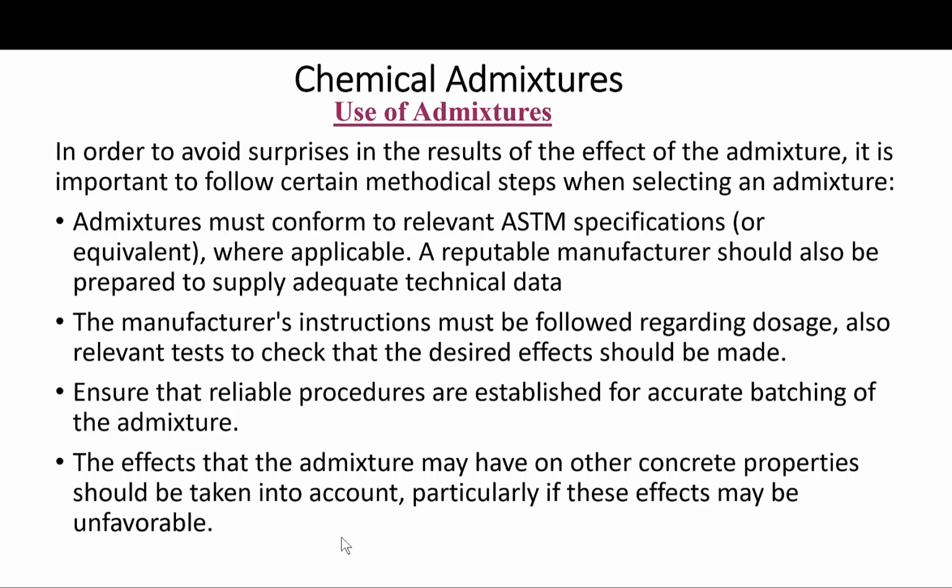So the admixture specifications, based on the fact that the chemistry of these admixtures is really complex, and you cannot really set certain values and figures in stone. So based on that, the admixture specifications are performance specifications, and basically what that means is it sets minimum changes in the property of interest, for example, the decrease in setting time, and limits on how the other properties should change, for example, strength. And again, it sets limits but no set figures.